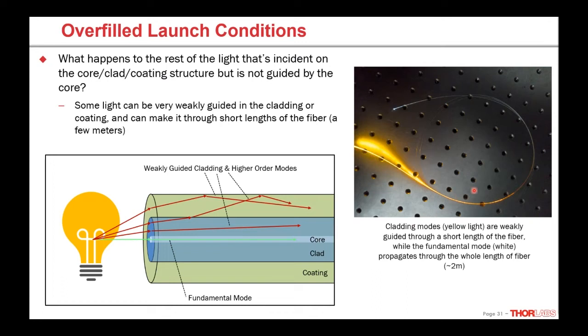Here what we did is we have a few meters of single mode fiber. It's single mode in the visible region. And we've hooked it up to a white light supercontinuum source. And you can see at the end of the fiber, this white light at the tip, that's light that is coupled into that fundamental LP01 mode and propagated through the whole length of the fiber.